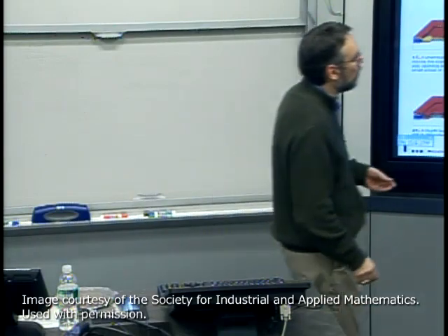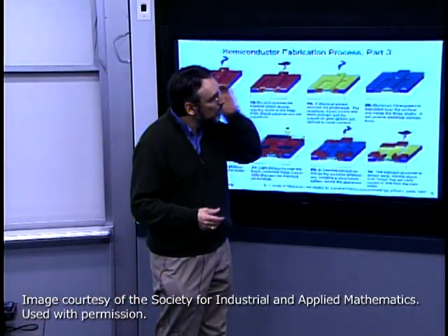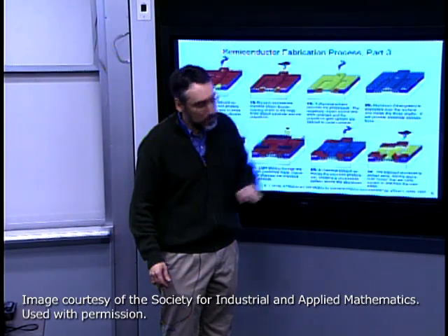The metal source, aluminum or other materials, will be heated up either directly electrically or under sputtering kinds of activity, such that either individual molecules or small agglomerations of molecules become very excited and trajectory through the vacuum and build up the layer on the surface of the wafer.